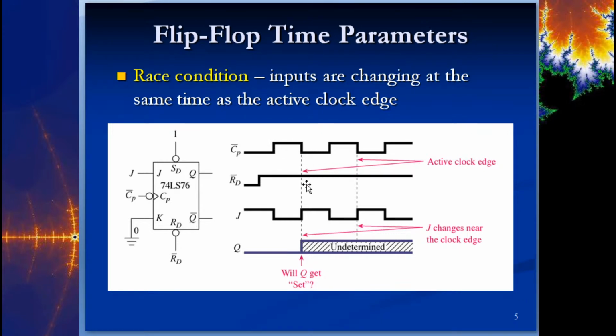At this one point in time, J and K are being accepted on the input. Now, K is 0, so really the only condition here is either a hold or a set, because you can either have 0, 0 or 0, 1. Initially it has an asynchronous reset that pulls to 0. You can see that here, and that's why the output at Q is 0 here. It has an initial state.